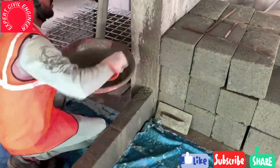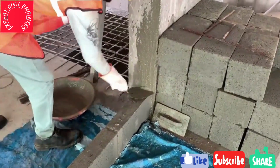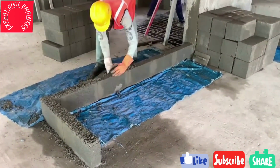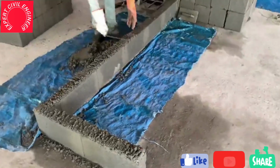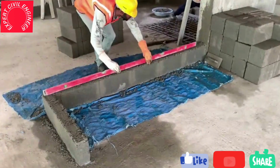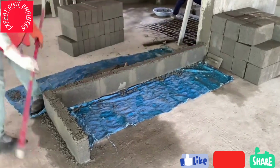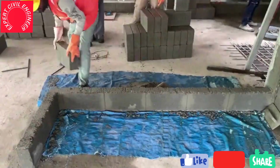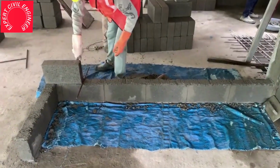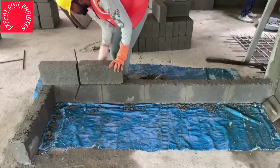A 1:1 ratio of cement slurry should be applied on the column to ensure proper jointing between the RCC and blockwork. Bed mortar should be applied on the first course of blocks to establish subsequent layers of blockwork. Ensure leveled mortar application with uniform bed thickness throughout the blockwork. This should be verified using a spirit level. After completing the leveling of the bed mortar, ensure that the blocks are placed on the marking course, and stagger the pointing of the marker course and the first course of the blockwork.